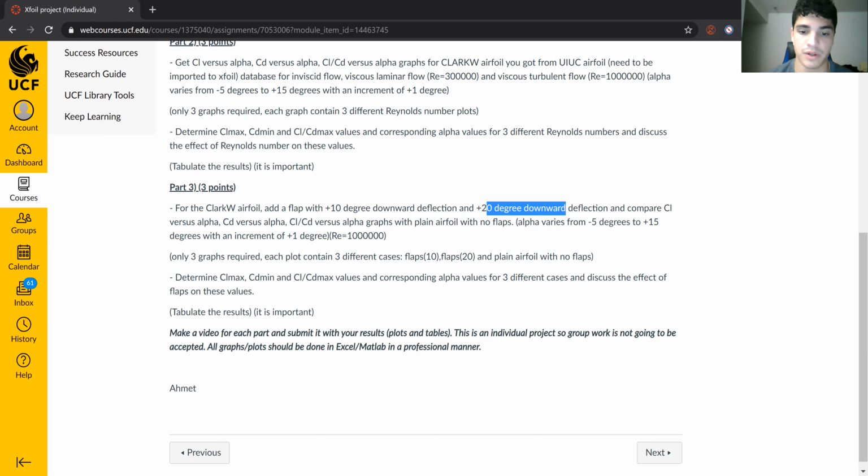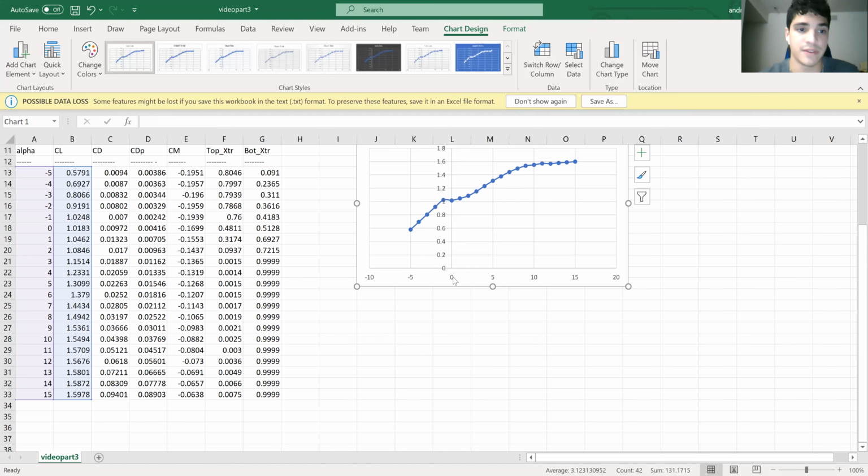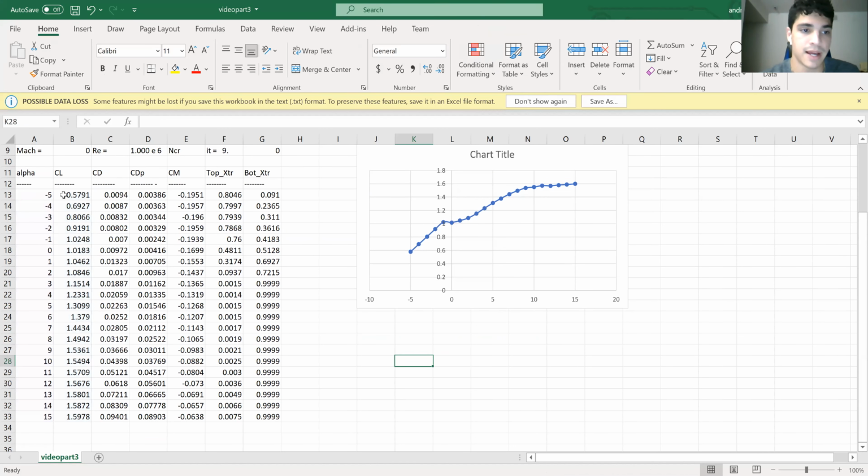But you're going to get the same alpha and CD, max CL, min CD results for that. So if we go back to our video part 3, let me share that. We do that for this one, and then you're going to get your max from here, which is going to be 1.519 for our CL. Your lowest CD is going to be at -1, which is going to be 0.007.